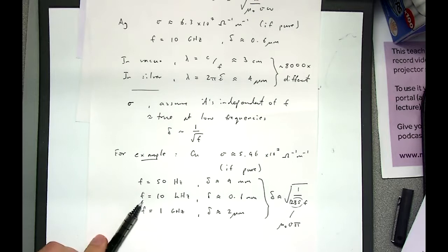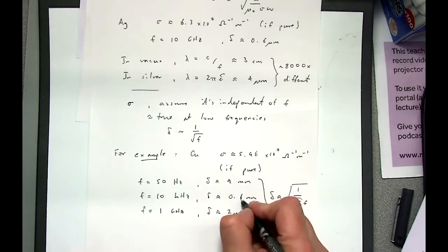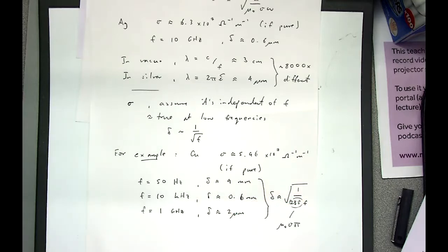And as you can see, as I increase the frequencies that I wish to transmit along the wire, the skin depth gradually decreases. So if I want to carry a certain signal, and a certain amount of power, and I might be limited by resistance or other things like that, what I need to do is subdivide that single conducting piece into several wires, okay? Where I have independent surfaces along which I can carry the signal. So for example, your speaker wires don't have to be big and thick to carry an audio signal. They only have to be about 1 millimeter in diameter or so.